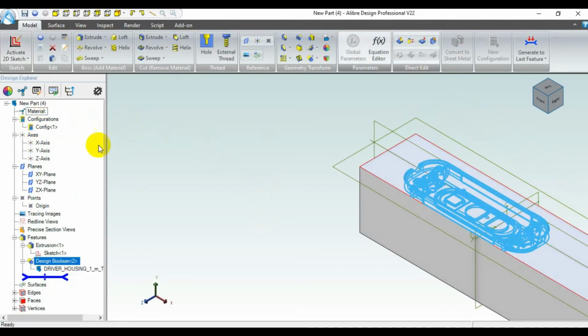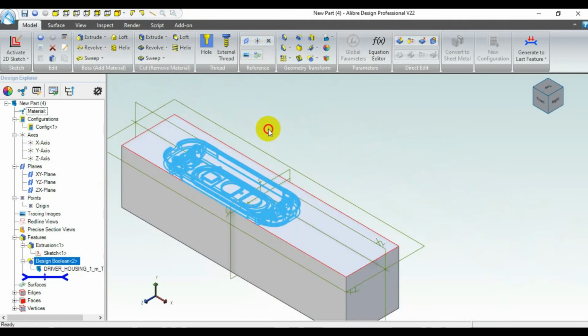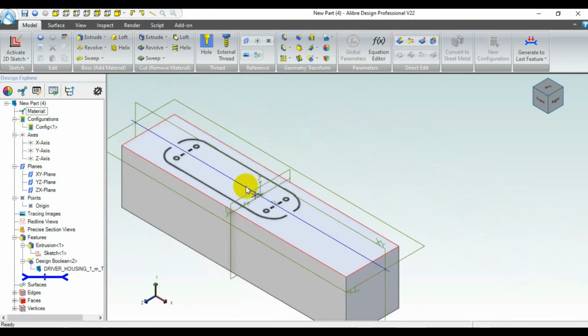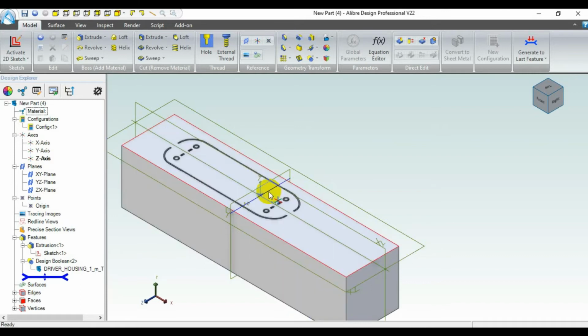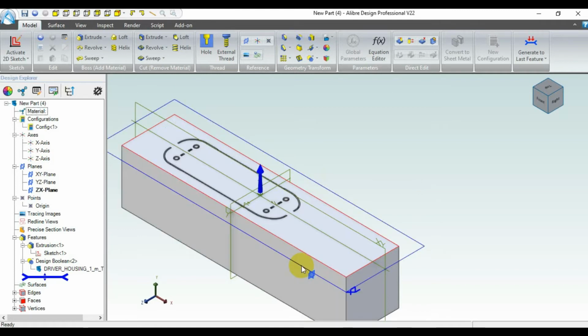So there's my part buried in the cavity block, but what they're about to tell you in the instructions is how to remove this section here, which would have to be on the core side. We call this side here the fixed side of the tool, because it doesn't move, and the side with the ejection on and what have you is the moving side. So this is the fixed side of the tool where the plastic is ejected from. But we want to remove this particular part here so that we can make a working cavity here.